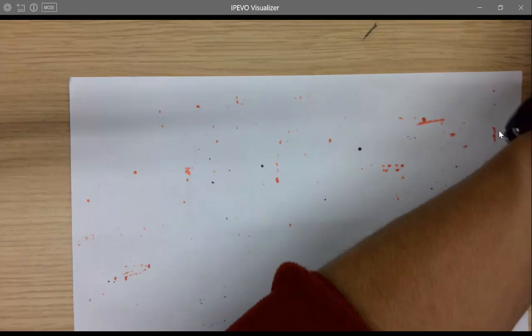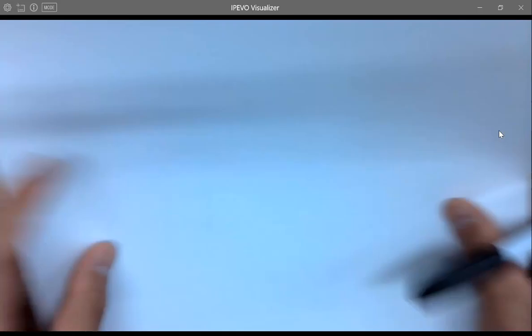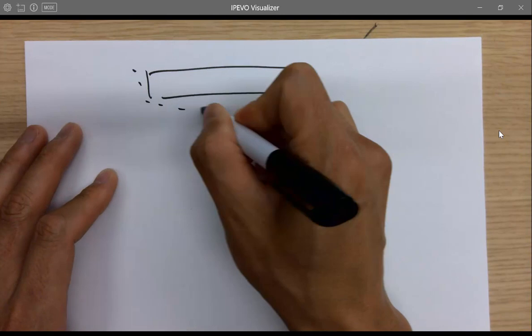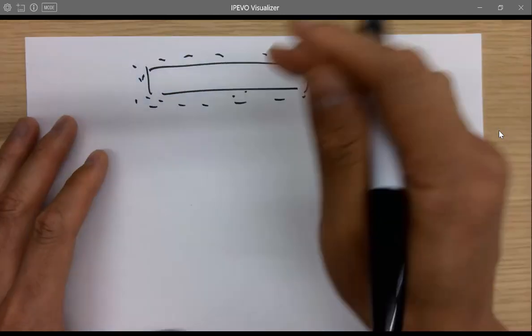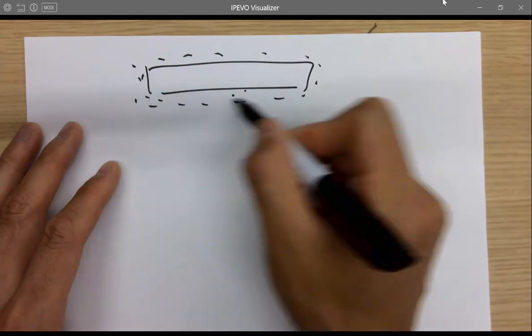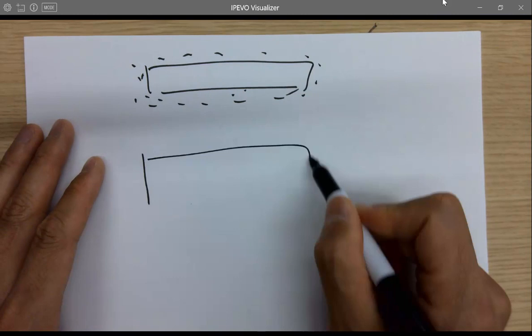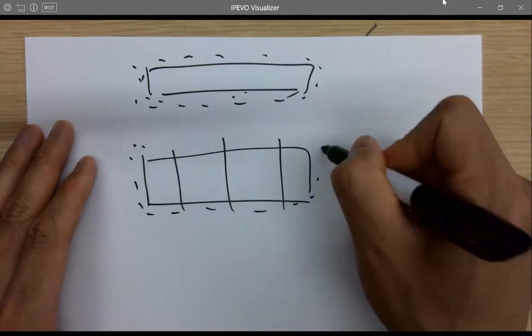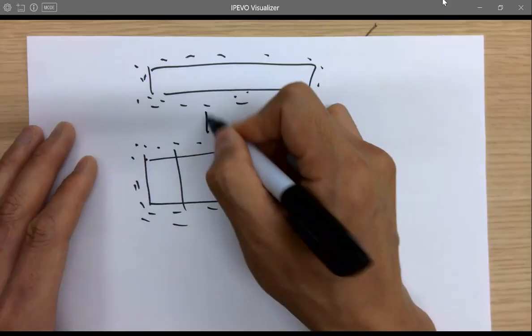If I don't draw that pure rectangle shape in the middle to bridge them, do you know what I'm saying? So I got an N-type on the top, right? It has all the dots. So the dots came with that part. I grabbed it from the library and it has a ring of dots. And the PMOS, I grab a few PMOSes, and it has a ring of dots because the PMOS are supposed to be built in the N-well by default. But there's a gap.